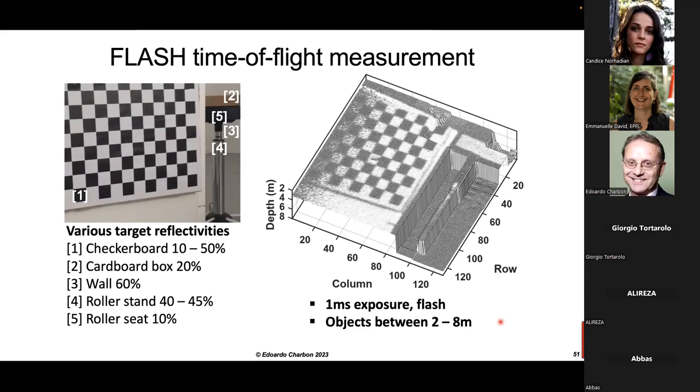That's T. P is very, very limited. P refers to process variation because it's a digital process. And so the variations between components across very large chips even, it's in the order of a few picoseconds. So it doesn't really matter as long as you have ways of compensating or calibrating the TDCs. So this is variations across the chip, and variation from chip to chip are even less concerning if calibration is in place. But calibration has to be in place in some way.